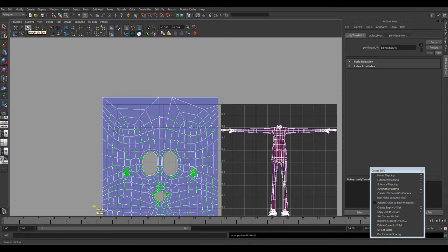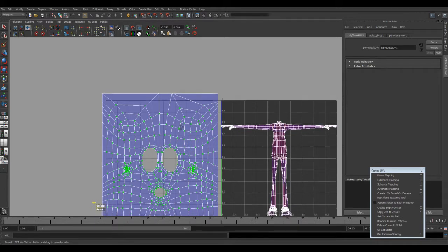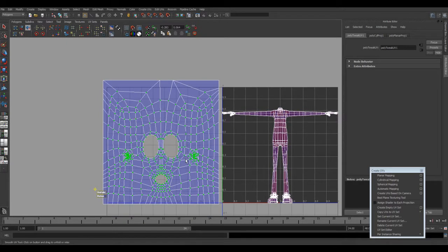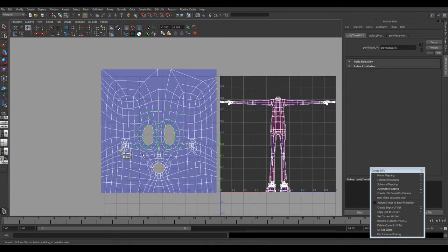So this tool in particular, this Smooth UV tool, is particularly useful for spreading out your verts in a very organised way. Sorry, not verts, your UVs. And the advantage is you can select certain areas and keep working on it until you're happy with what you're getting. So again, these two tools work in conjunction with each other, but it's there to spread everything out.